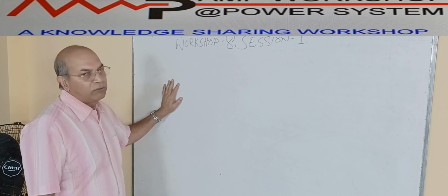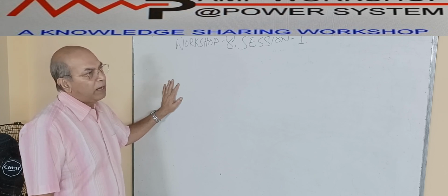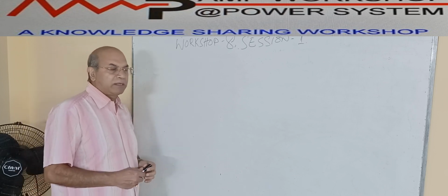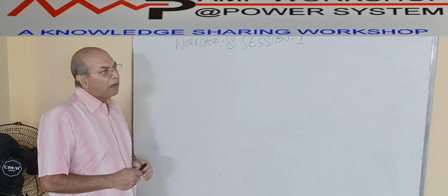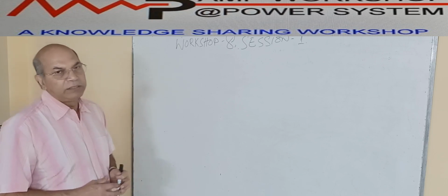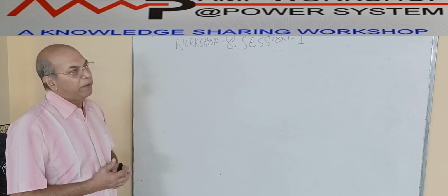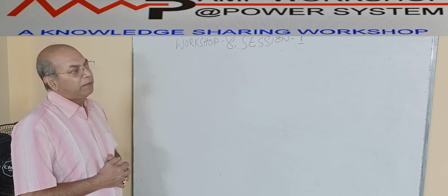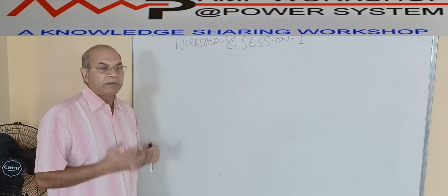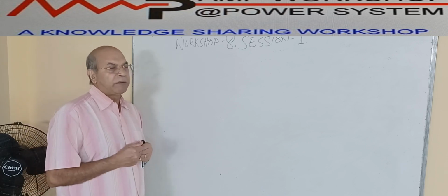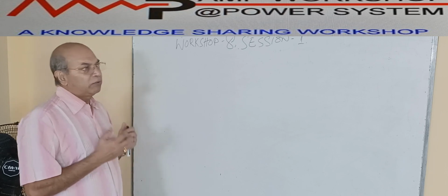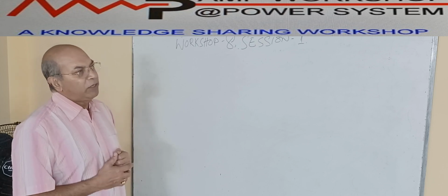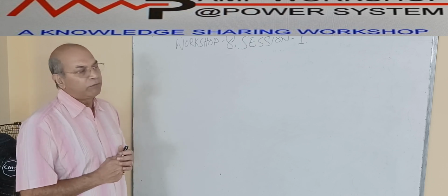When you look into the medium voltage or high voltage switchgear, it has two parts. One part is the power part, another part is the control part. The power part is how the generators, or the power generating company or utility, give power supply to a particular switchgear. That is the incoming power coming to the switchgear. The switchgear has a busbar arrangement which receives this power, and after receiving the power through the busbar, the switchgear distributes the power to the various outgoing loads. This is the way a switchgear works.